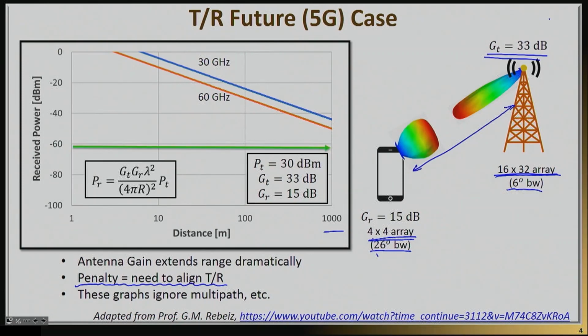Before we were able to make antenna arrays inexpensively, the only way to do that was by literally mechanically moving an aperture, which is not very interesting. With antenna arrays, on the other hand, as you're moving, I can relocate the beam to hit you in the order of nanoseconds or microseconds. And not only this, but I can have independent beams for different users. So beamforming approaches are very advanced today, and that's why this concept actually works.